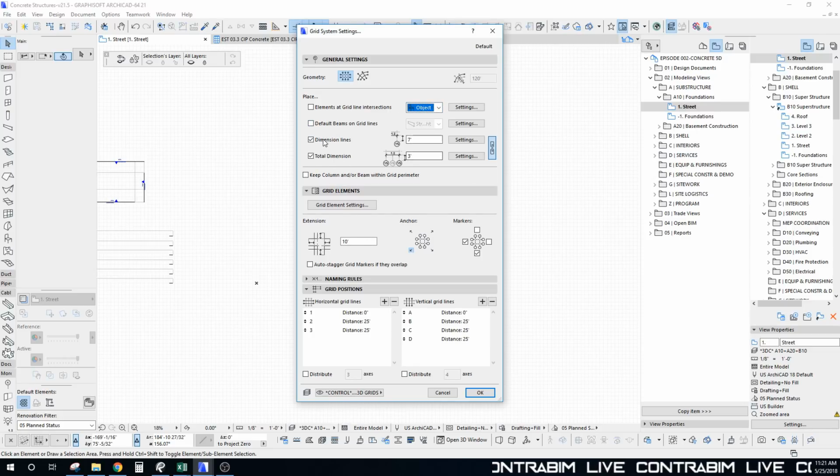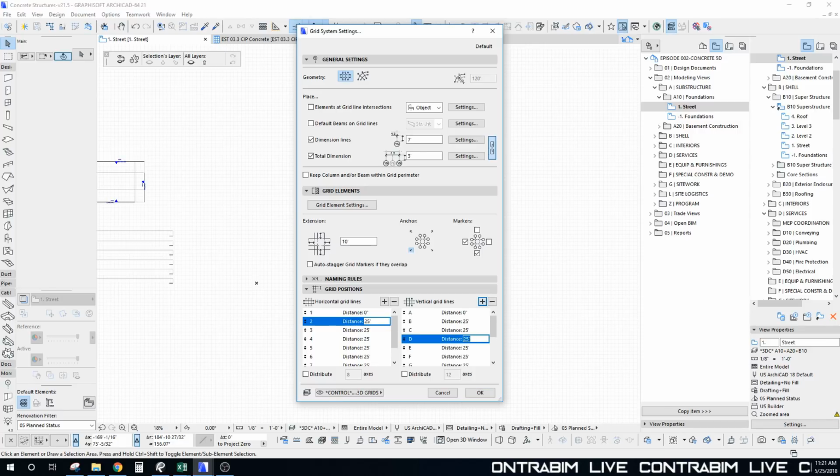Same thing with beams. We're going to leave those out. We can certainly just leave the dimensions. That's fine. And then we're going to anchor. I always like anchoring things from the bottom left corner because I like placing that right on my 0 point. But to make this video faster, instead of focusing much on design and tweaking of dimensional type things, we're just going to use a standard 25-foot grid in both directions and make it really quick and easy to model and copy things around, so that we don't waste a whole lot of time trying to make small adjustments.